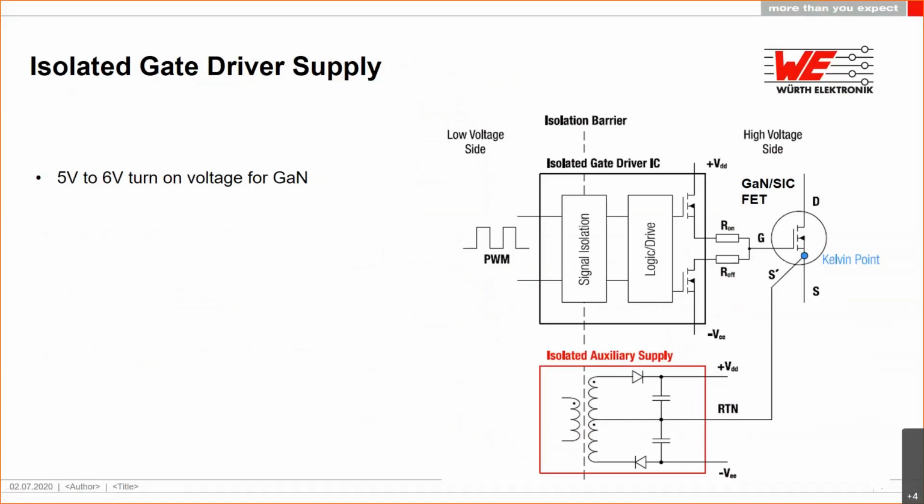First we have to look at what voltage levels we need to drive a GaN or a SiC FET. For example, for a GaN device without any internal driver, you usually drive with 5 volt maximum gate source voltage. The devices can handle 6 to 7 volt at maximum, but you need some headroom for ringing due to the parasitic inductance in the gate loop and the gate driving system.